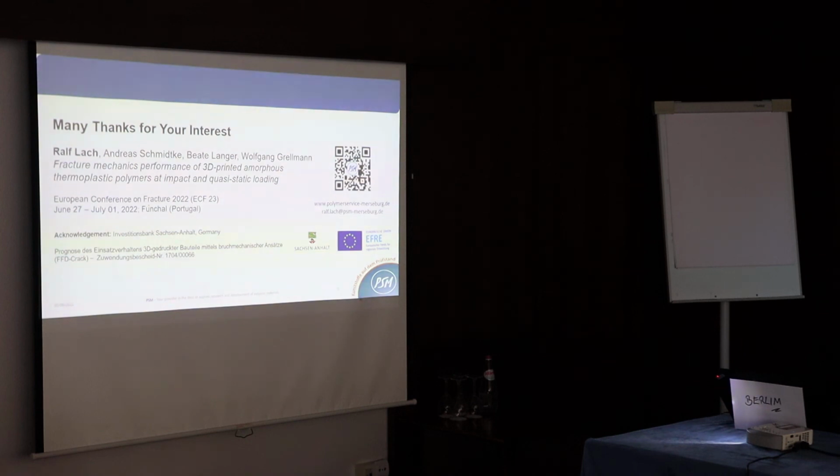Did you measure your mechanical properties as a function of test rate, not the printing speed? No, the test rate is also changed, because 1 millimeter per minute is quasi-static and 1 meter per second is impact. We did not do it for this. I did a lot of work before on ABS, so we did it in ABS too, and also polycarbonate, and changed also the speed. But this was not part of this work.